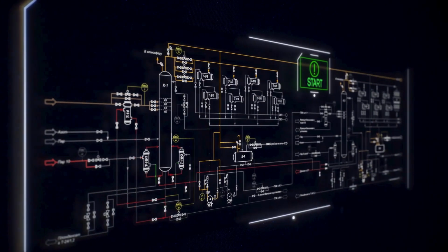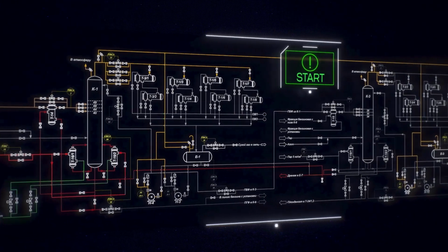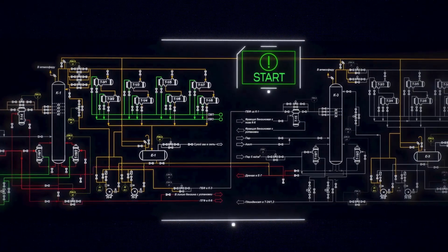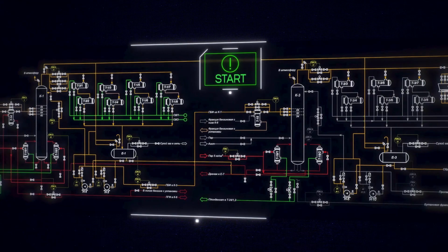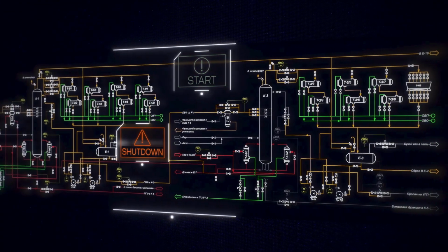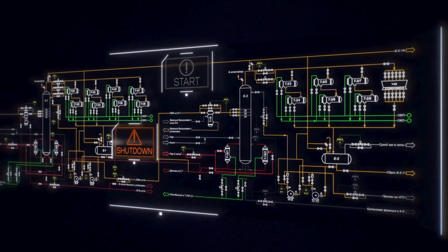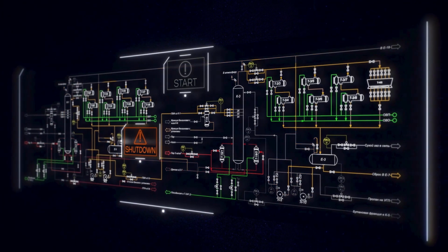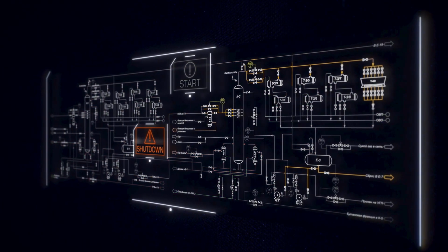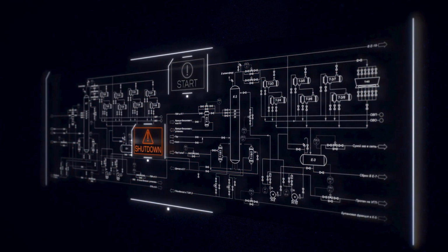When practicing actions in abnormal and emergency situations, as well as during startup and shutdown of the installation, it is essential not to limit actions to the scope of the distributed control system alone. Equally important are actions on site and the interaction of operators working at computers and in the field.